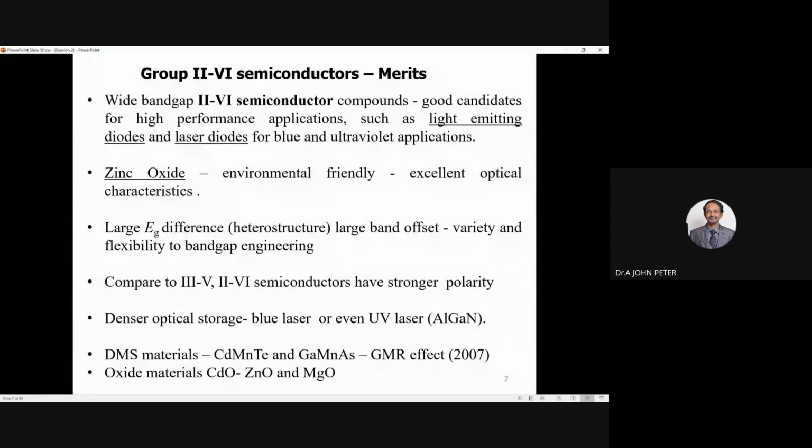When you are going to use your semiconductor, you dope it with some magnetic impurities like Mn, or some other magnetic impurities. Fe, you can have. So these Mn materials are impurities, and CdTe, when it is added with Mn, will become CdMnTe, dilute magnetic semiconductors,